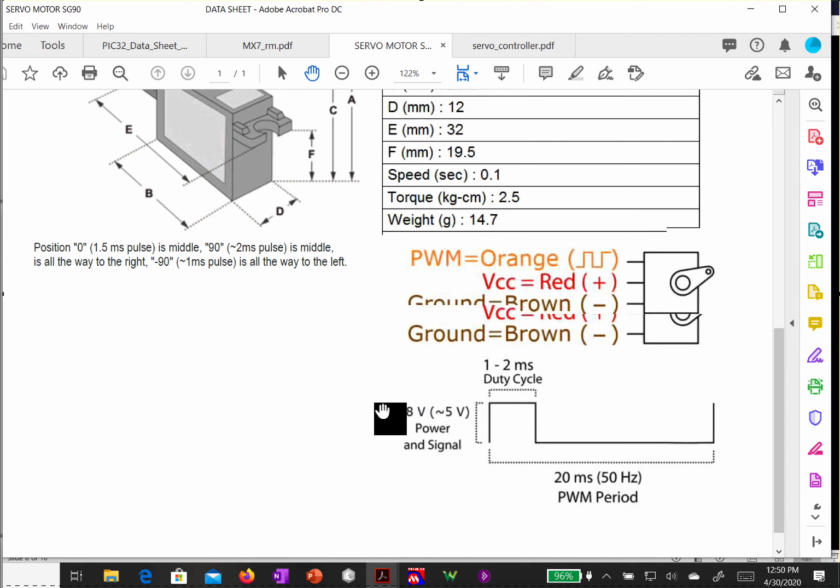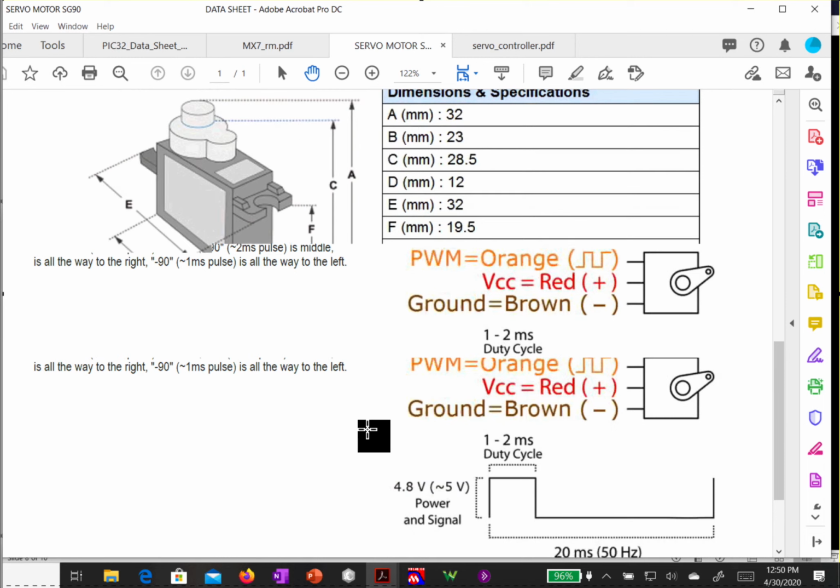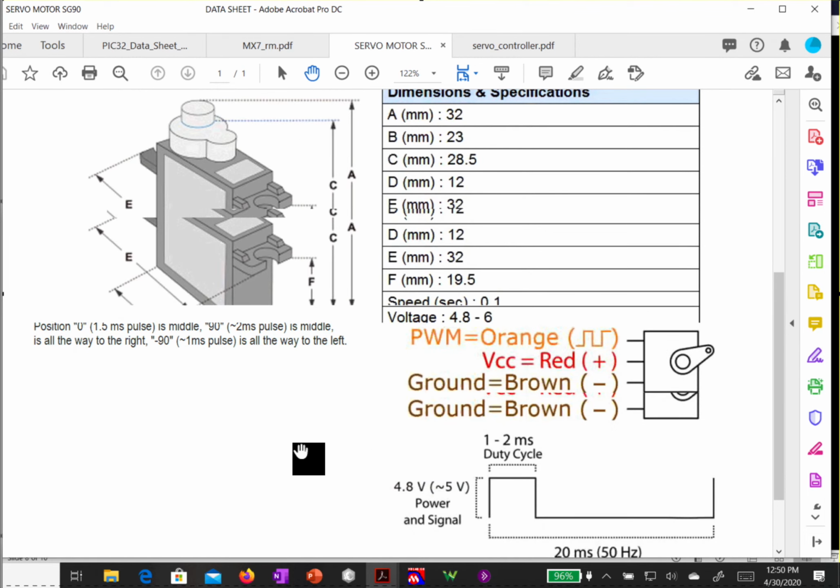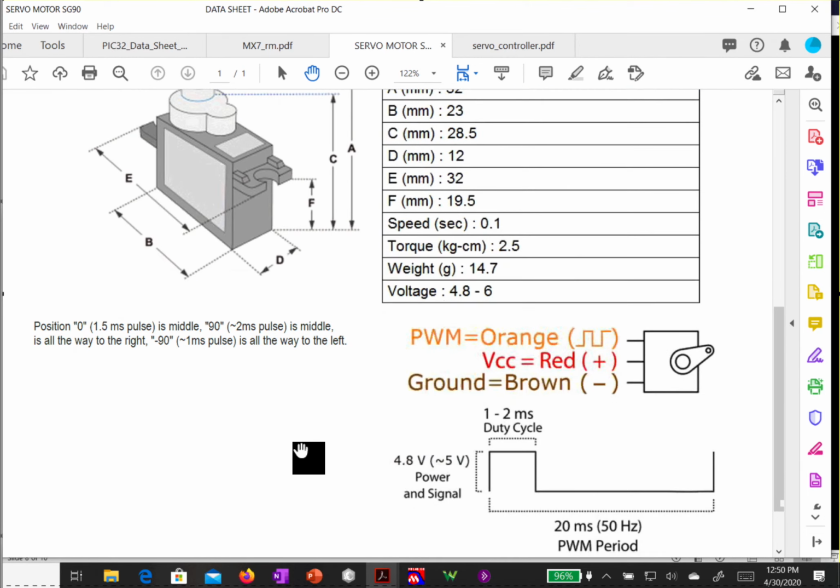Now, if I'm going to use a system with multiple servo motors, so for example, let's say I want to steer all 4 wheels independently, then you'd say, well, we need a number of output compare circuits. And oh, by the way, maybe these output compare circuits aren't perfect, we need external circuitry to be able to drive motors. One of the things about motors is they tend to take a little bit of power.